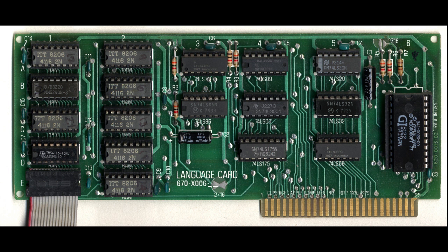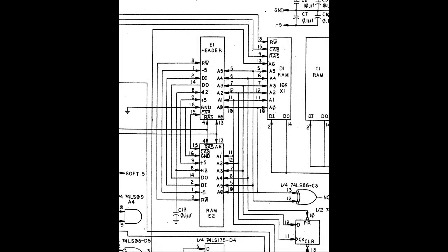And the reason is that dynamic RAM needs to be refreshed, and it needs address multiplexers to work, and a two-phase select with row address select and column address select. All the circuits for refresh are really on the Apple II motherboard, and also the address multiplexer chips are on the Apple II motherboard.